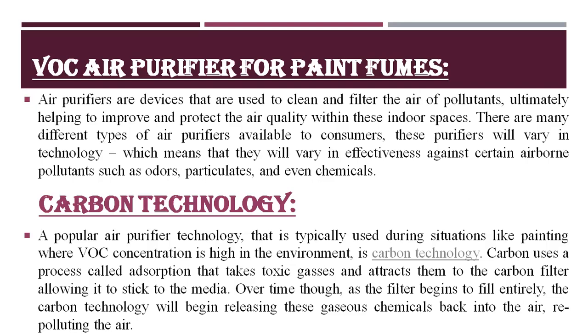Carbon uses a process called adsorption that takes toxic gases and attracts them to the carbon filter, allowing them to stick to the media. Over time, as the filter becomes saturated, the carbon technology will begin releasing these gaseous chemicals back into the air, repolluting the air.